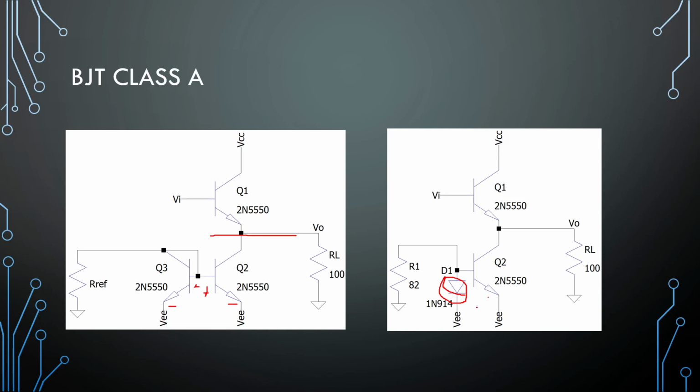So it can become a bit tricky, but you will see configurations like this with a diode included and some form of resistor. The best way, however, to do this is to use matched transistors. So I'm going to go with the example on the left in our calculations.